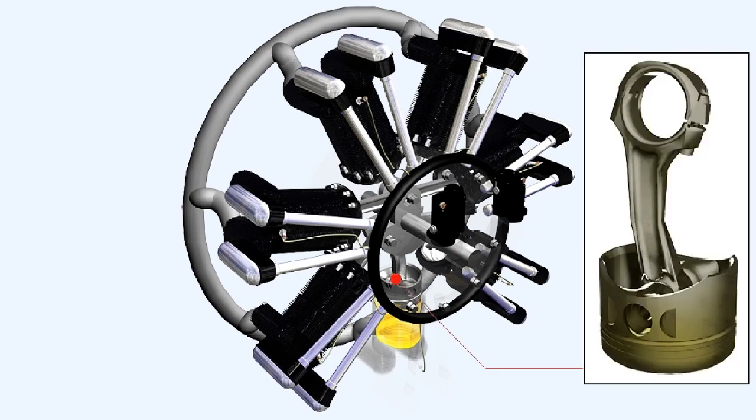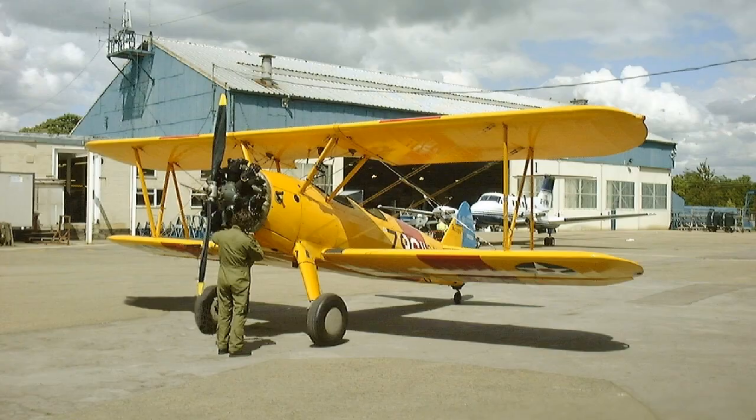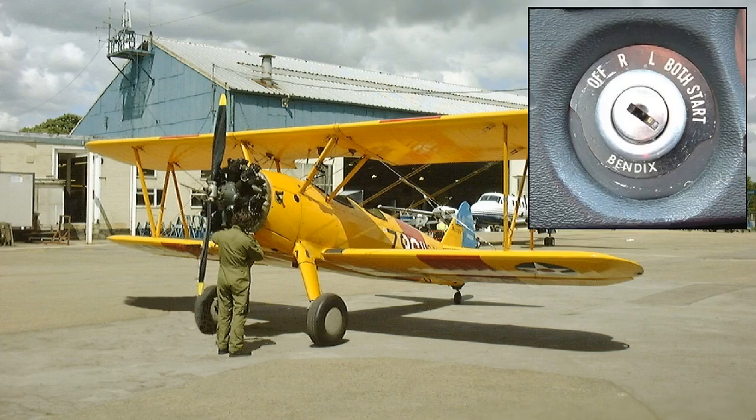Damage to the engine could occur on startup, as the piston, on the compression stroke, traps the incompressible oil between itself and the cylinder head. Prior to starting, these engines should be rotated through a number of cycles by use of the propeller to ensure no hydraulic lock has occurred. You must, of course, ensure that the magnetos are off before turning the engine over.